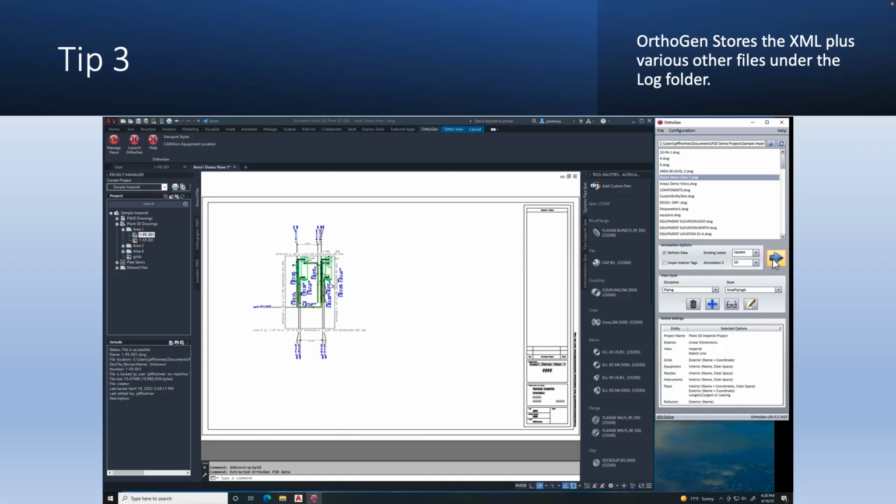So the last tip is really kind of an insight into that log folder. If you're having an issue and you haven't been able to resolve it by setting your diameters, your drawing units correctly, or making sure you're pointing to the right project file, and it's time to talk to Marcus, do the DDS ver, find out the version number, and then look in this log folder.